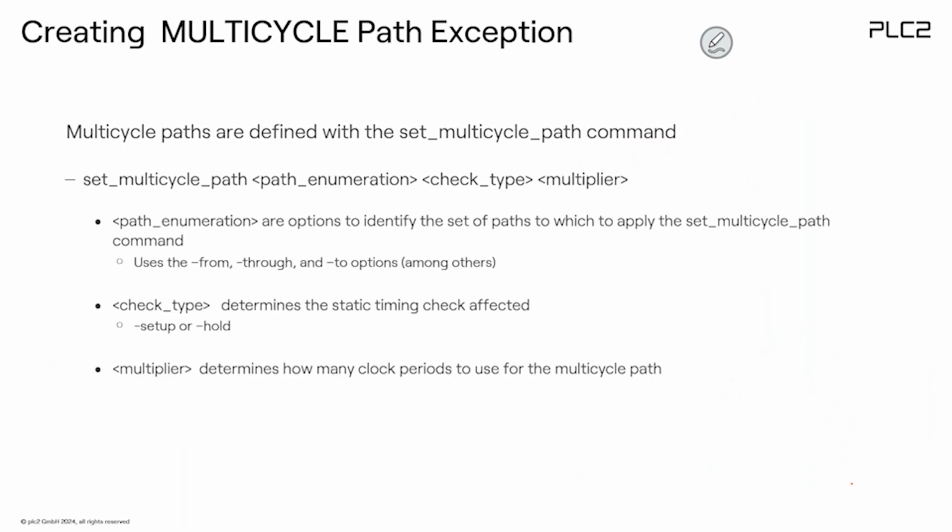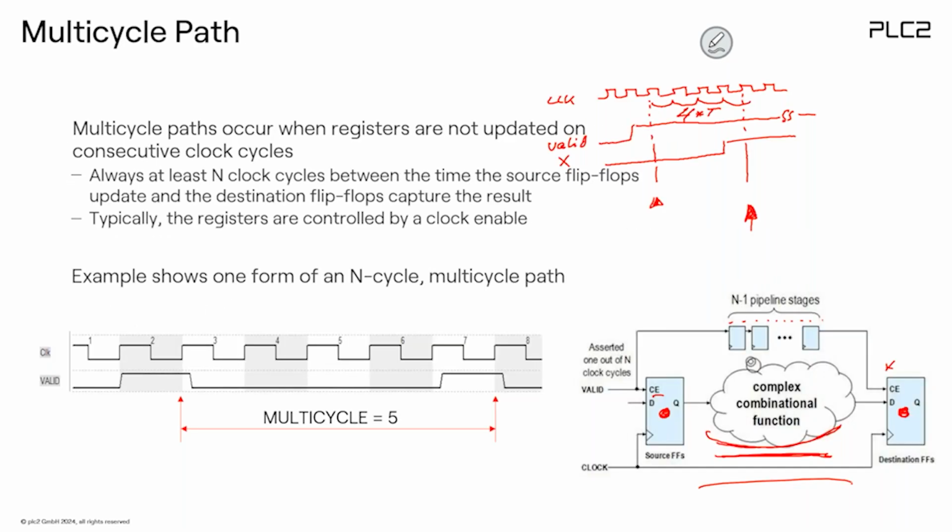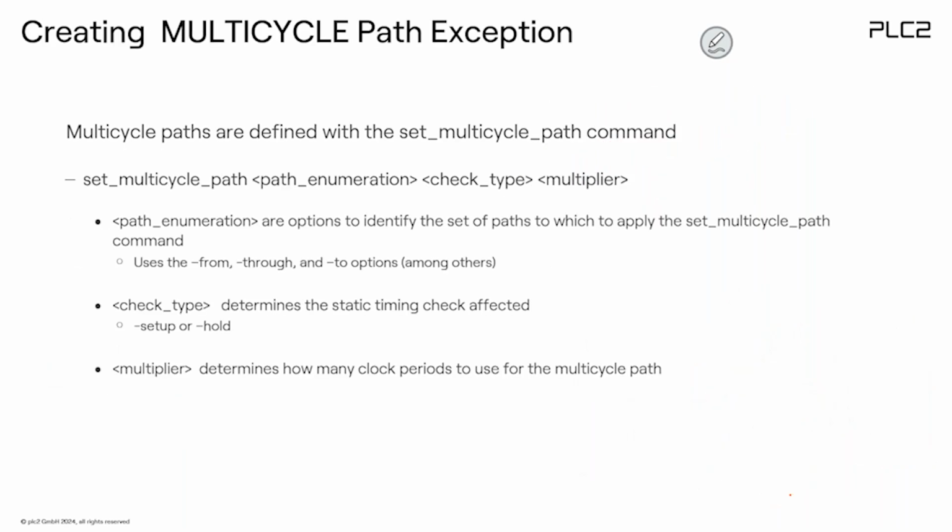This makes your life very easy. You can say, from flip-flop FF1 to flip-flop FF2, you have 5 cycles of time, and then this specification is relaxed. I don't need to hurry, I don't need to make this possible at 200 meg. I can have 200 divided by 5, which is 40. So I have 5 clock cycles of time to do the job, which makes it very easy.